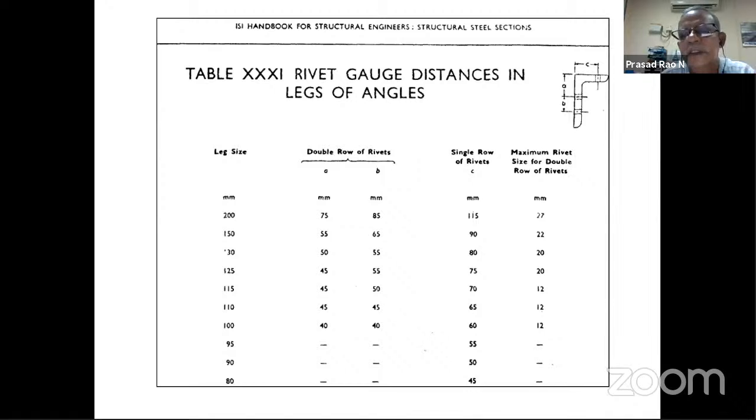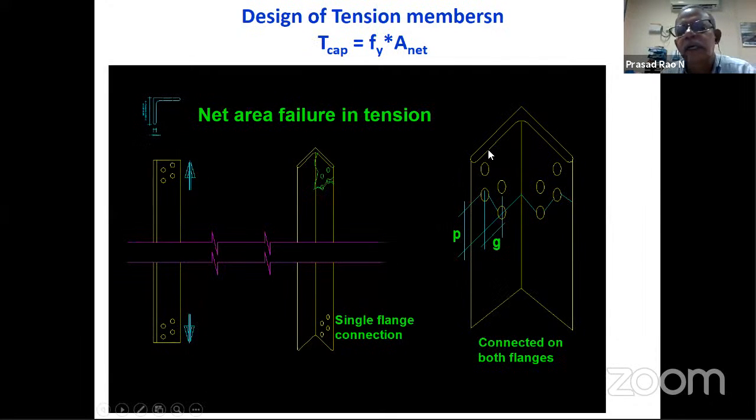We can stagger the bolts in such a way that there will not be any failure of block shear and other failures. As a typical angle section subject to tension, how will the failure path be? You see this is the critical path. Suppose you take the first one, top: you have one bolt here, another bolt here. So directly you deduct 2 bolts from the gross area.